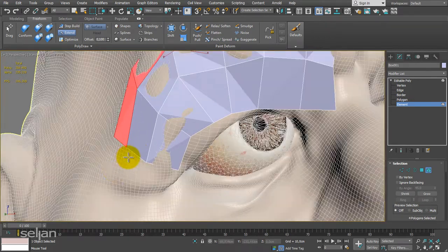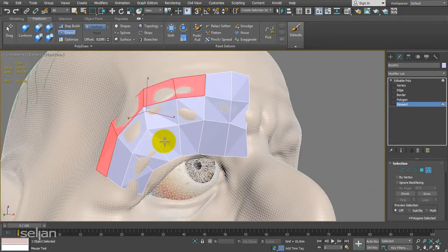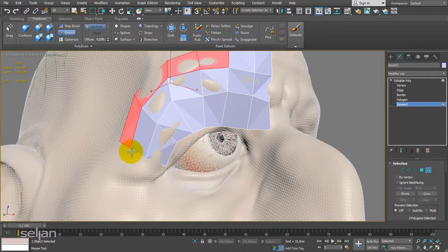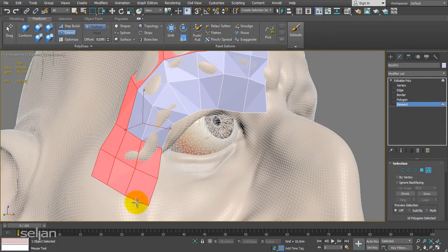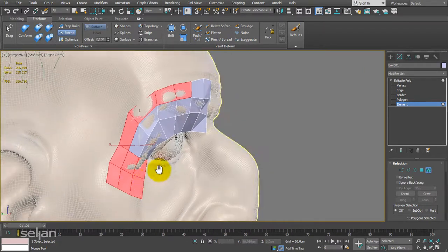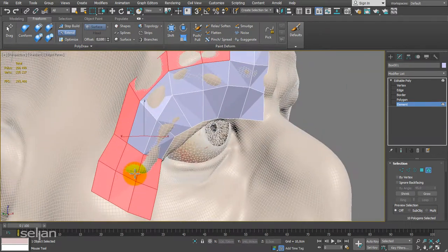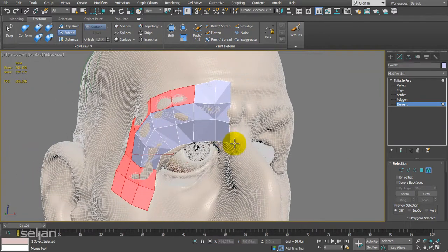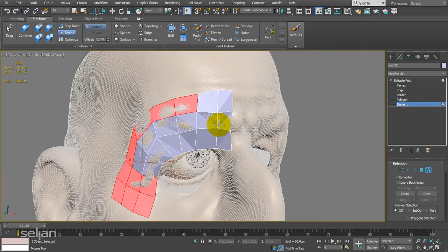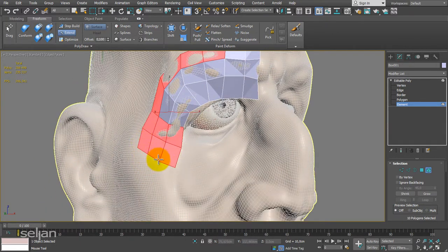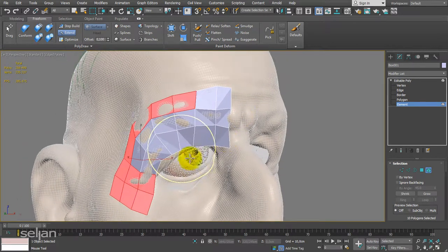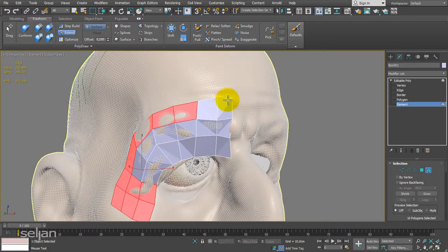It's cool. If you want to make it a little bit faster to build up something like this, you can use Ctrl and Shift, and Ctrl Shift can extend multiple edges, so edge loops are actually extended. Now when you're dealing with this, you have to be careful because it selects all the edges in the loop. So if you have longer edges, right now it's not that long because it's only 3 segments, but here I have at least 8, 9.